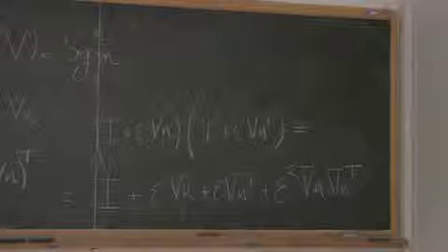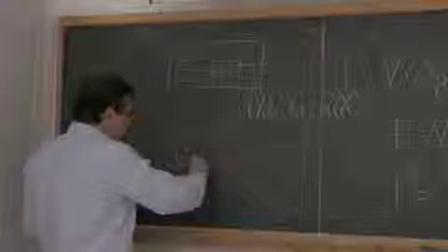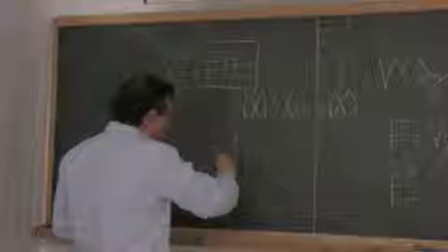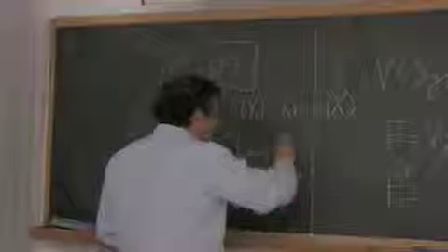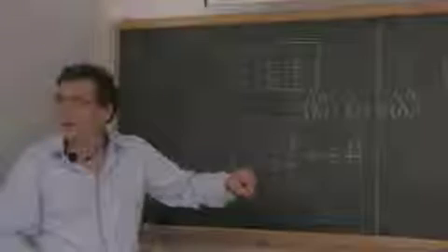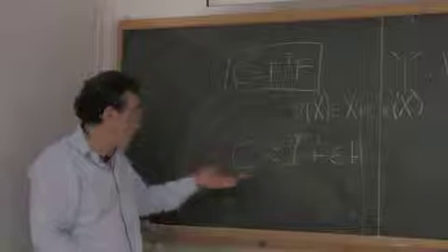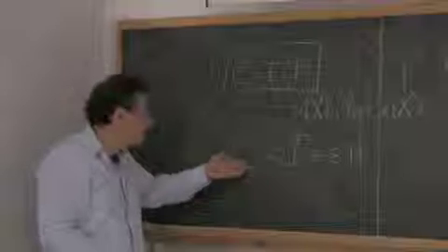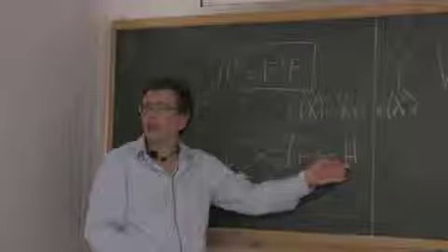So now you are starting to understand where we will go. Instead of C, we can write C nearly equal to identity plus epsilon H, where H is grad U plus grad U transposed. And in our constitutive equation for deformation energy, for instance, instead of C, we can use epsilon H.